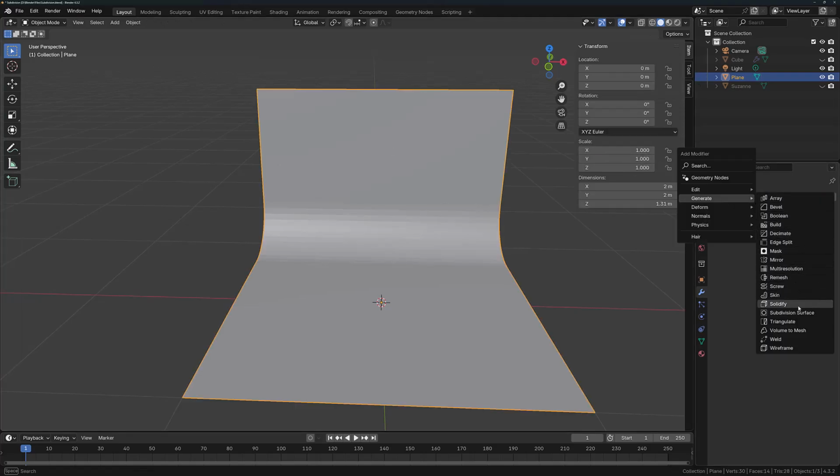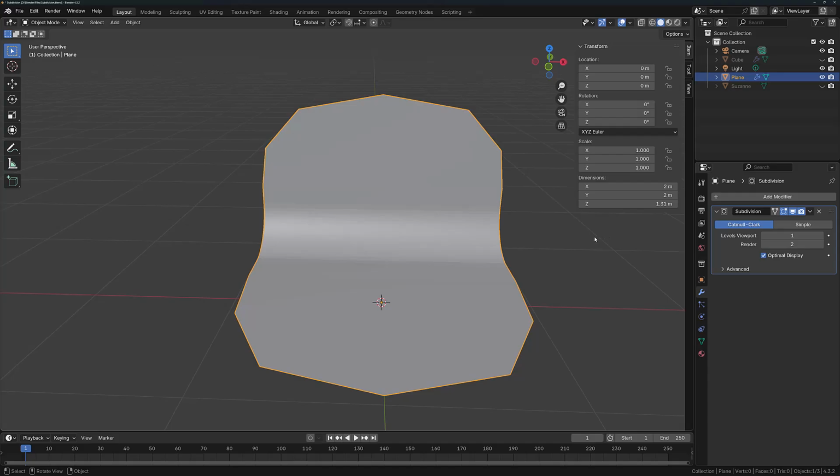If we add the Subdivision Surface Modifier to this example and open up the advanced settings, we have the Boundary Smooth property. By default, this is set to all, which means it's going to smooth all of our geometry, including the edges used to make the boundaries. If you want to remove this, you can just choose the Keep Corners option.